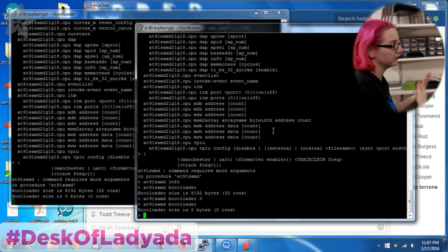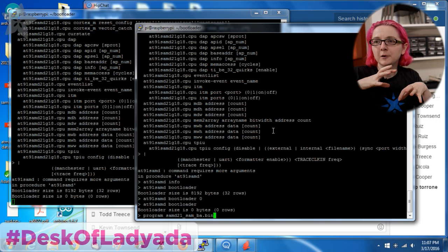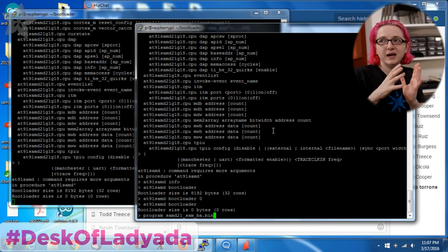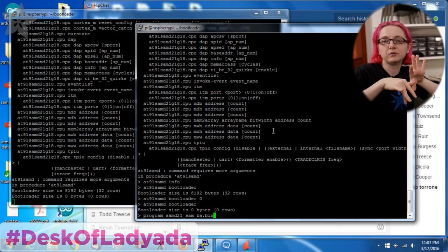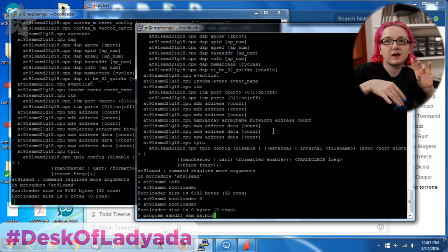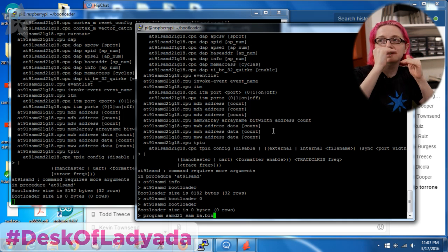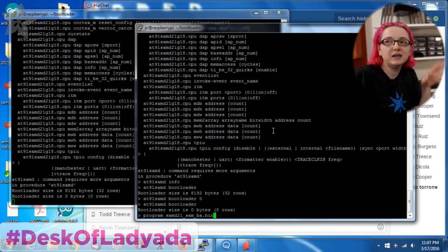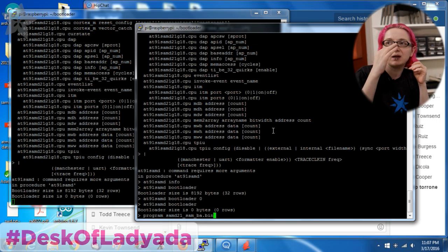And then you say, okay, do you set the bootloader? And then let me try programming now. I'm going to have to do a reset. You have to figure out for each chip, I've determined there's this kind of magical thing where it's reset, halt, chip erase, reset, unprotect, reset, do another erase. You have to learn what the magic command steps are, because this is all hidden in something like Atmel Studio. They don't tell you the commands that they're sending.